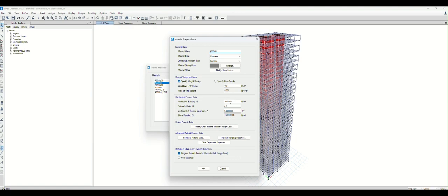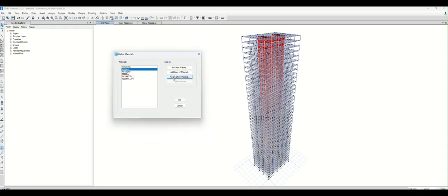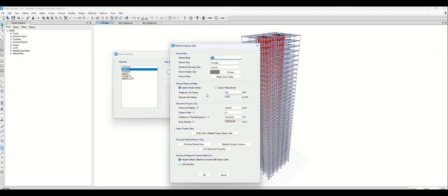Most likely we're going to change the Young's modulus based upon concrete strength. What we'll do is copy the 5000 concrete. I'm going to call it C5, simple and short. For Young's modulus, either we can type it or use the internal calculator. I'm going to type an asterisk and SQRT, because Young's modulus is proportional to the square root, so 5 divided by 4.